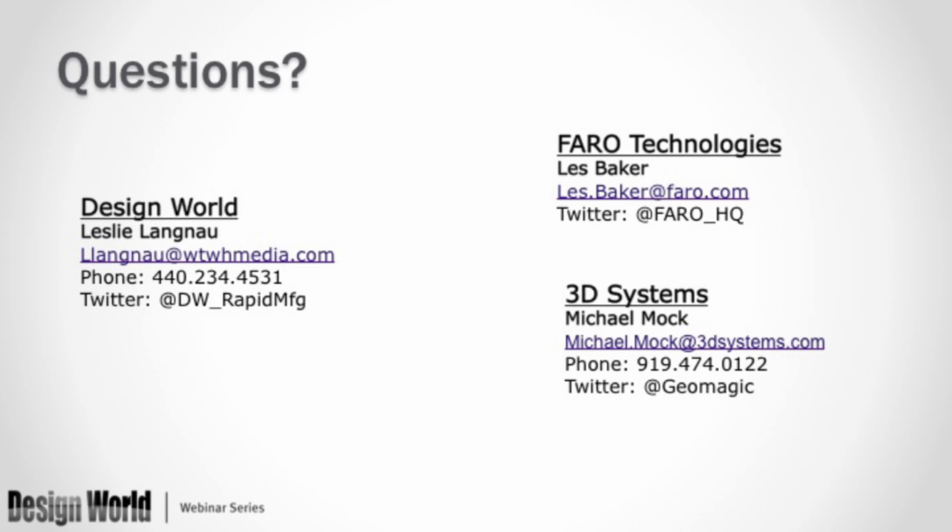Okay. I think this one is for Les. Do you need targets or dots for scanning? With the handheld laser scanners, because it has a localizer that tells it where it is in space, no, you don't need to have targets on the part. Those targets are usually there so that images that are captured in space can be stitched back together because there's no other reference for them. But because the Faro Edge arm always knows where it is in space, it tells the camera exactly what it's looking at, and we actually capture a 3D point cloud rather than a succession of 2D point clouds that then have to be manipulated together.